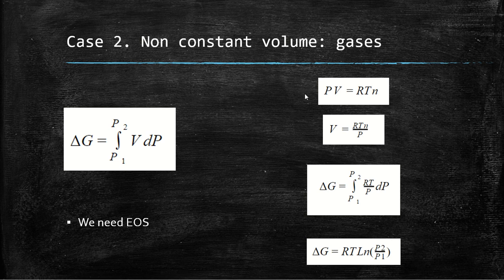which is stated in here, where we have PV equals nRT. For this we can note that we can solve this for V, having all the terms be something that you can take out of your equation, because it has in here the P variable that is going to be integrated, and you can take out R and T. But in here the n can be taken away, as all of your variables, like R and T, in your thermodynamic tables are stated as specific. So there's no necessity to add the n to the equation and it can be removed in here.